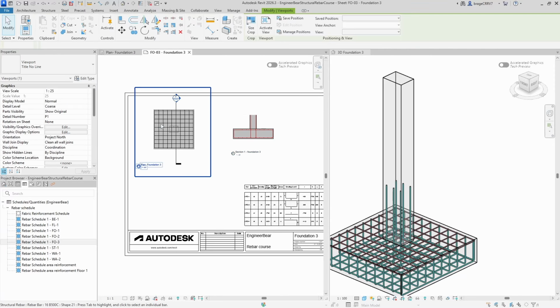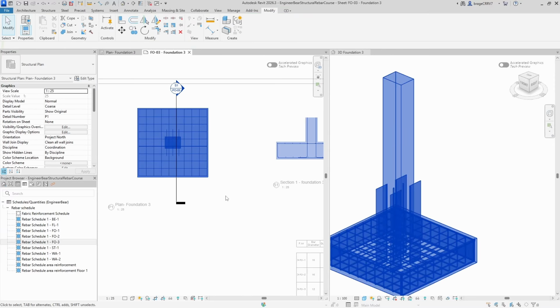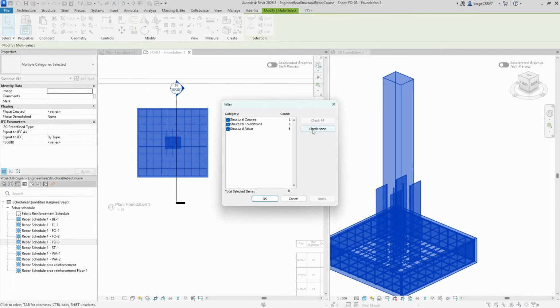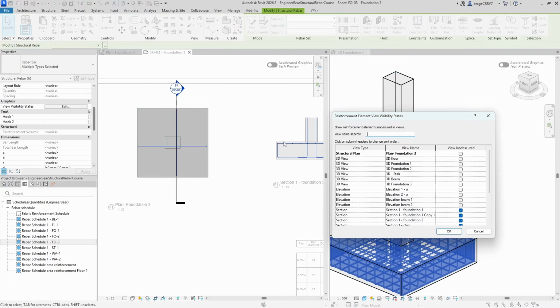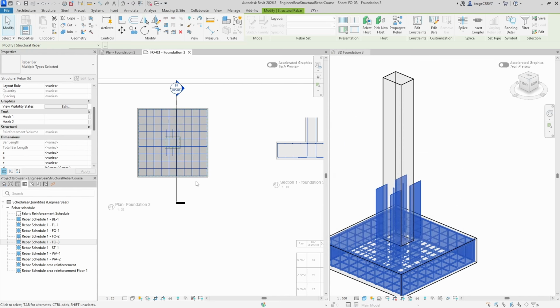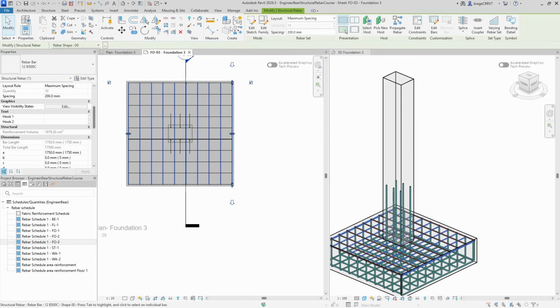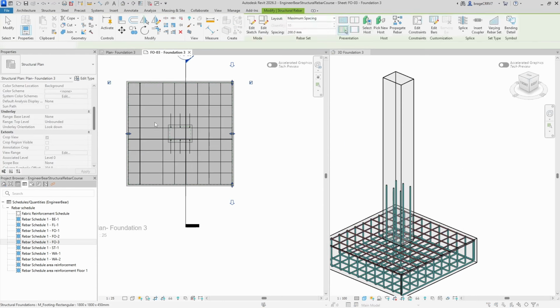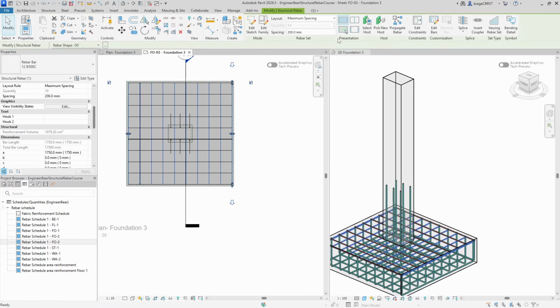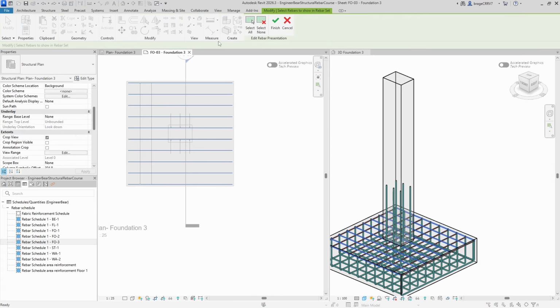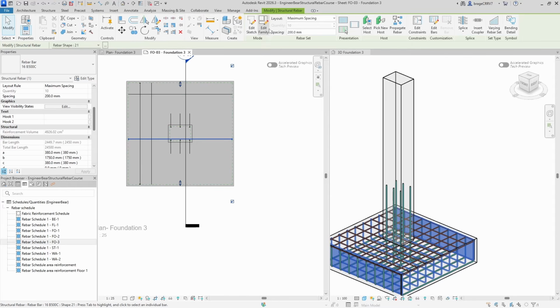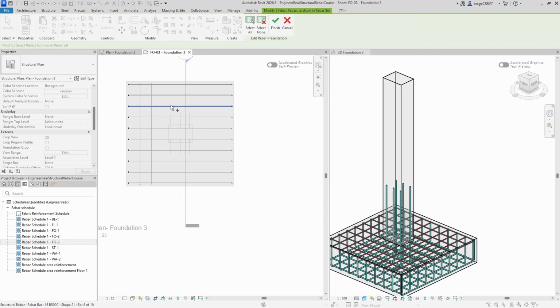that is tagging every rebar, giving the necessary information about each rebar placed, such as the number of rebars in the set, bar diameter, spacing, and rebar number. I will be using the annotation tool multi-rebar, which will both provide a dimension line and a rebar tag, making the process more effective. However, this is a tedious process, tagging every rebar.